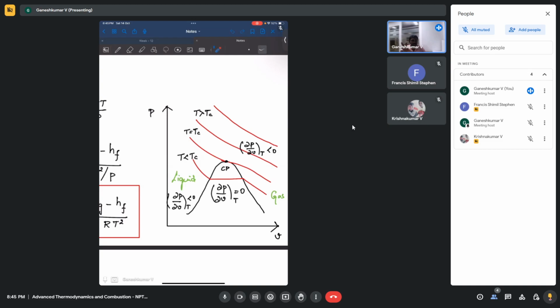and 50 megapascal and at a very high temperature, and all these things happen inside. Whatever we do is we will directly apply ideal gas and we will try to solve it. But really what happens is the supercritical combustion happens inside the engines. Even the solid propellant engines, but importantly the liquid propellant engines, there will be supercritical combustion.